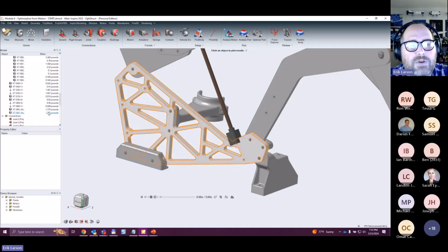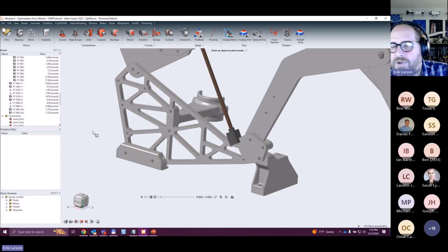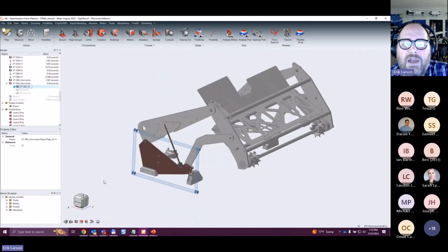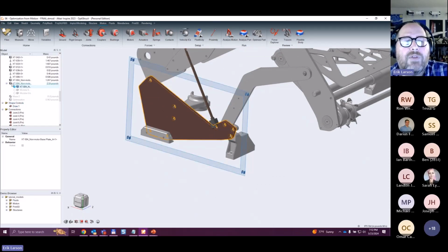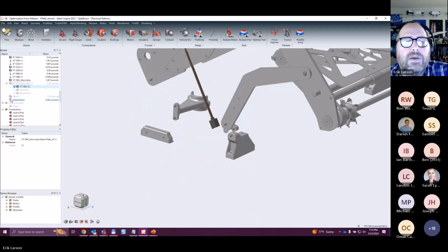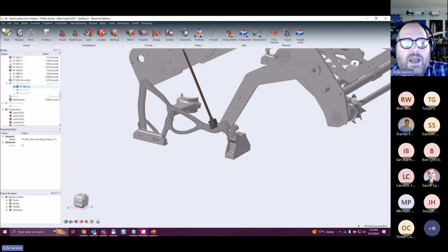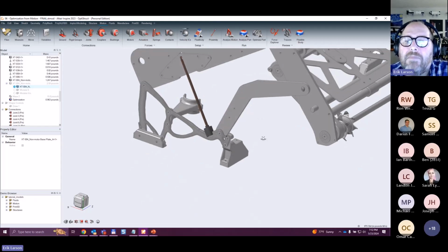You see each one of them, there's two on there, weighed a little over 1 1/3 pounds, 1.372 pounds. And that's fine, and it worked. But if we take optimization and instead use the motion to drive optimization, what I can come up with is this. And you'll see this weighs 0.963 pounds. So almost a 0.4 pound reduction in mass. And it was driven by a motion analysis.